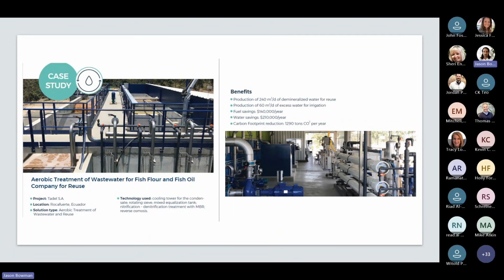The purpose of the split feed design here was to minimize the internal nitrate recycle rates. Given the high nitrogen value and the nitrate generated through the aerobic process, a normal MLE process would have required an excessively high internal nitrate recycle, which also equates to high energy consumption. So the step feed process helps to reduce the actual nitrate recycle compared to the incoming flow, or the ratio thereof.